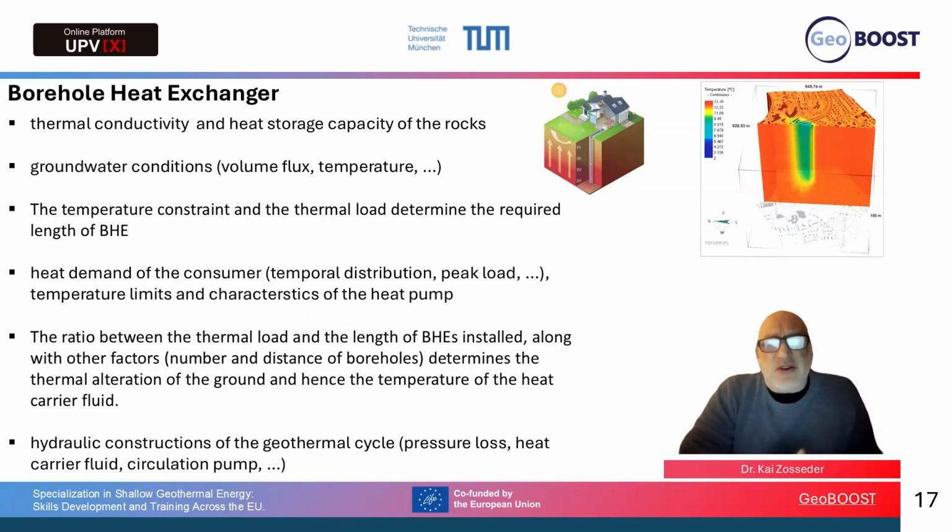What is also important is to see that the temperature constraints and the thermal load of the house determine the required length of the borehole heat exchanger. So the underground parameters, but also how much heat is needed to heat the house. This controls how deep we should drill a borehole heat exchanger. So we have to drill the borehole heat exchanger as deep as we need it to cover the heat demand of the house, of course.